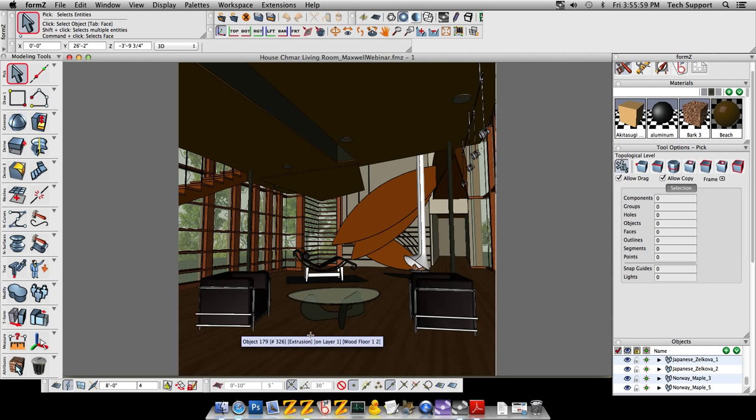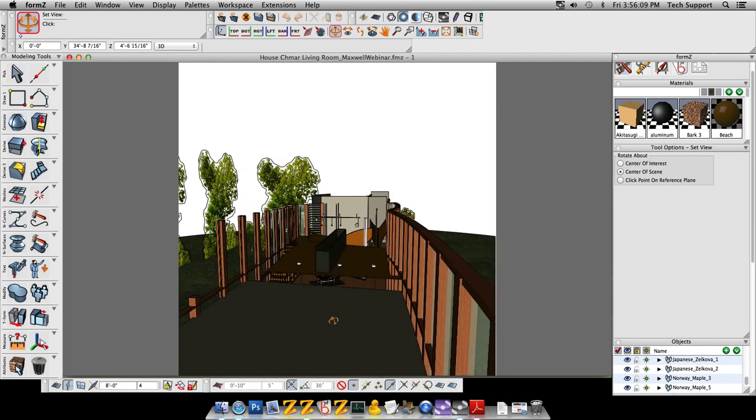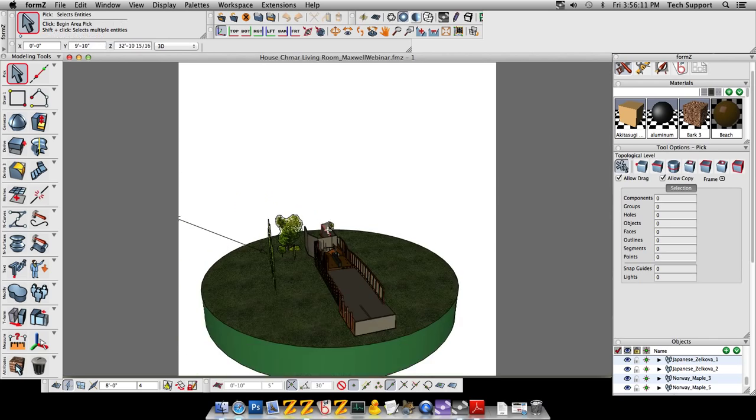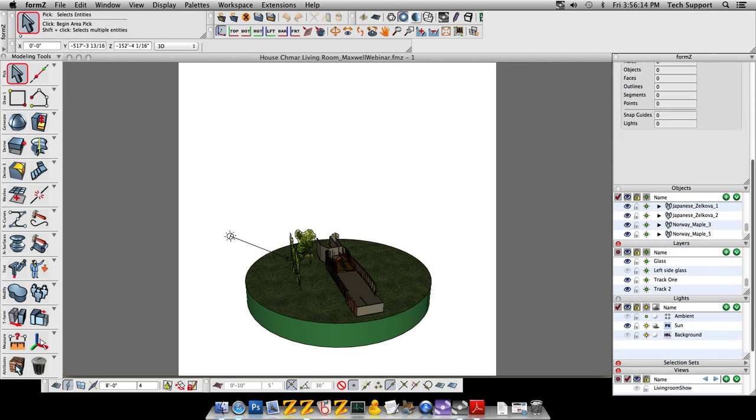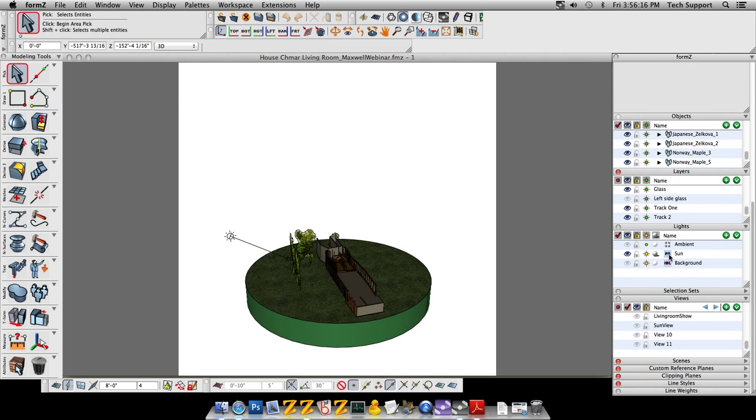Alright, so now I have an interior here, and I want to talk about the illumination setup here very quickly. Because I have a curtain wall of glass on either side, my approach on the outside is very similar to any other exterior render. If I want to look at my lights palette, I'll see that I have my physical sky set up, and I've got my sun.